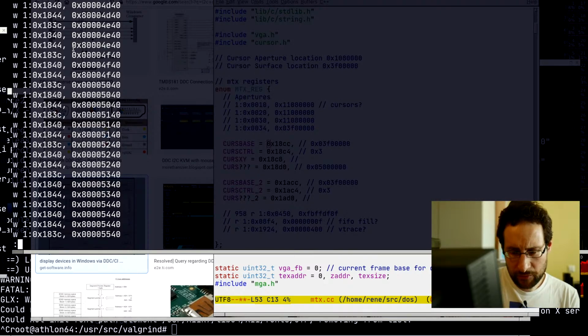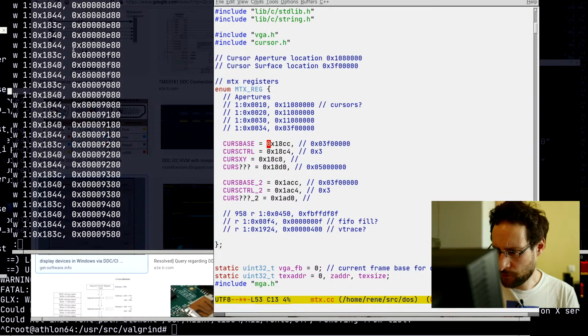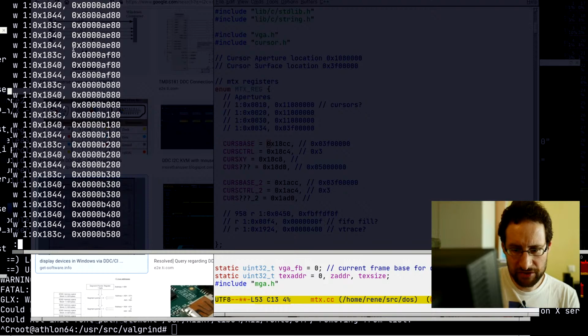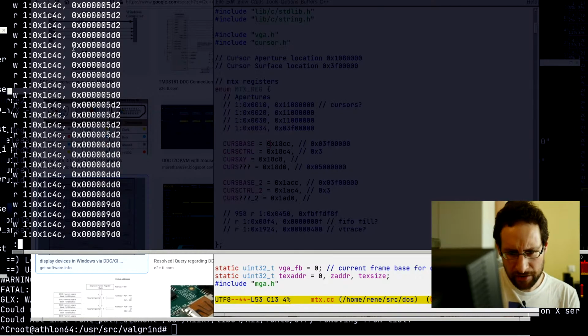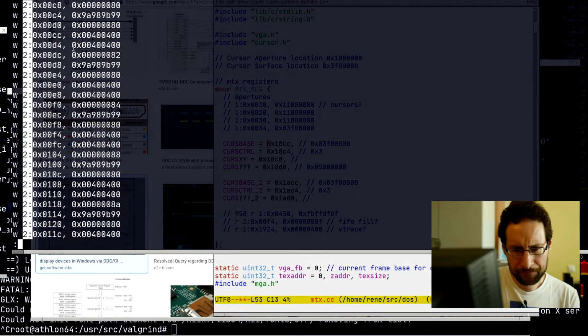So this is most likely phase locked loop, frequency programming stuff, and mode setting. Again, 1800 hex and 1A hex are the CRTs, in my opinion, from what I've seen so far. Again, all this fine mode setting bits to be decoded another day.